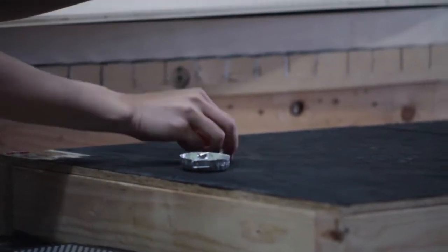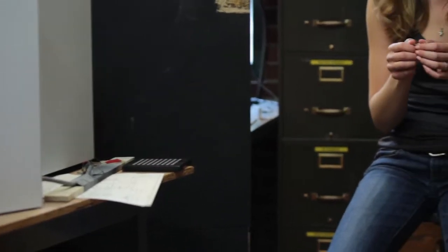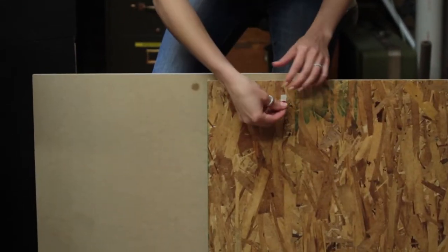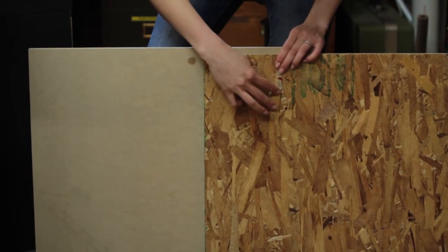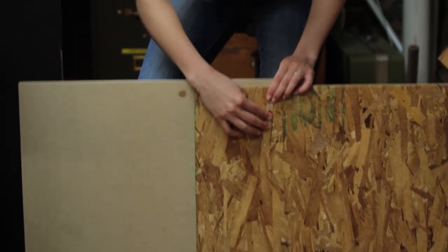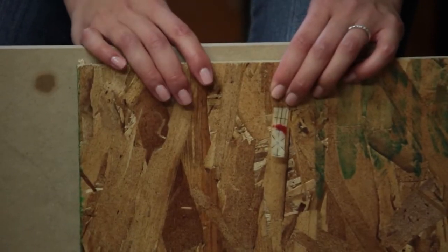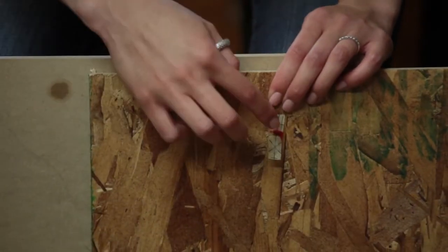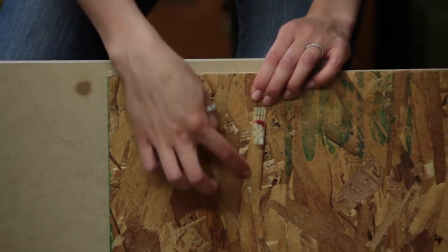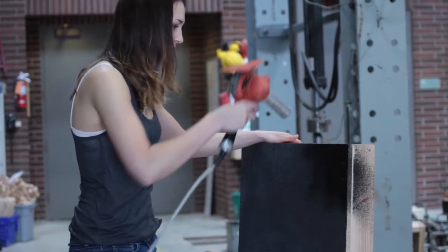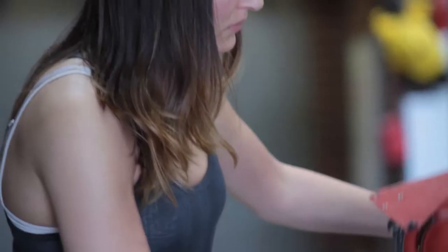You typically have two different types of materials that you use for sheathing in your wall. And the theorized problem with the strain gauge is that your small strain gauge can be placed only on one strand in your OSB, and that data won't necessarily be representative of the entire panel, because this flake could potentially move differently than the entire panel would move. And the DIC images the entire surface, so we'll probably get better results in the end.